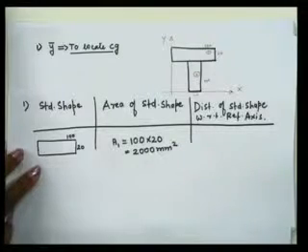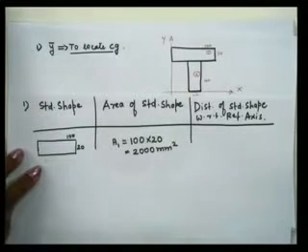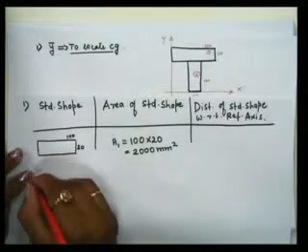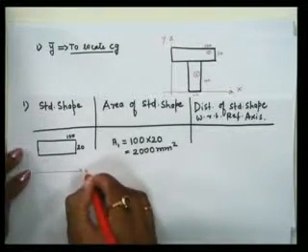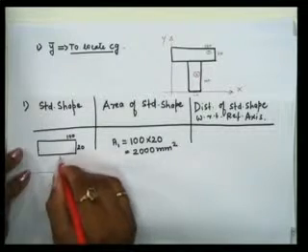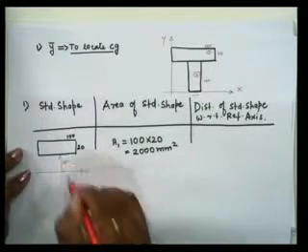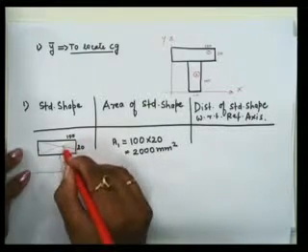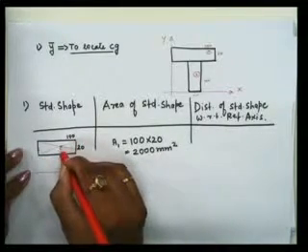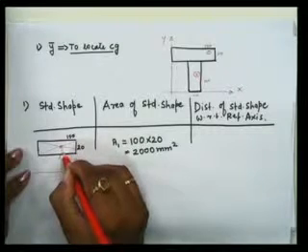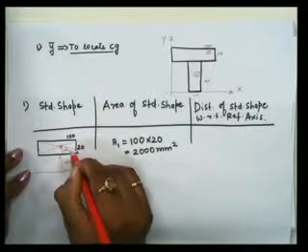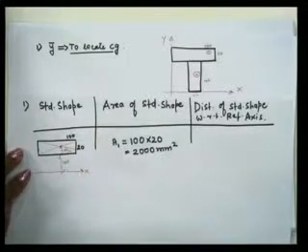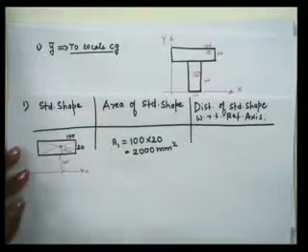Okay, now where is the reference axis from the first section? So somewhere over here we have got the x-axis. What is this distance? That is 100. Okay, what will be the CG of the standard shape? Intersection of diagonals, so this will be d by 2. So what is the y1?